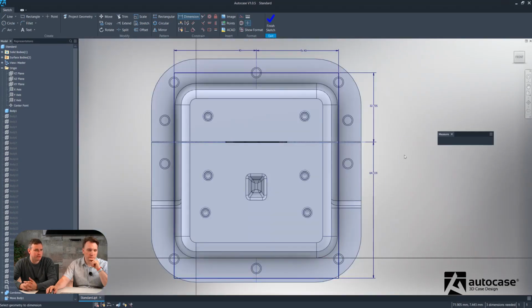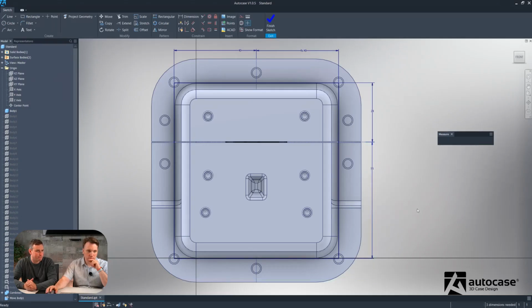And then we'll set those two dimensions, set the top one to about 28 millimeters as a starting point. And then the lower side, 55. And obviously you can change those, no problem. Final thing to do for this is to set the fillets around the edge. And we'll probably try a 10 millimeter. That should give us close enough.